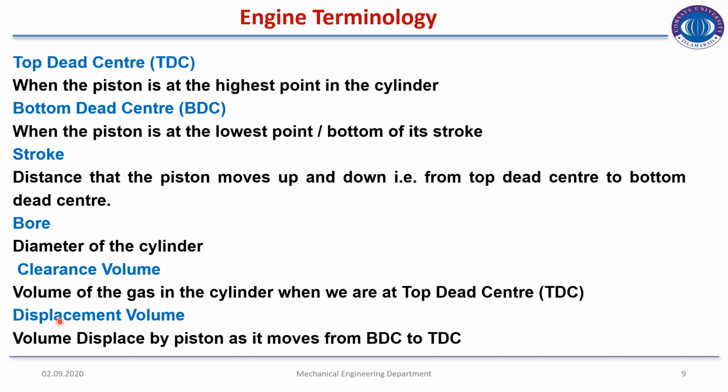Displacement volume is the volume displaced by the piston as it moves from bottom dead center to top dead center. As the piston moves from bottom dead center to the top dead center, it displaces some of the volume of the working fluid. That volume that is displaced is known as displacement volume.